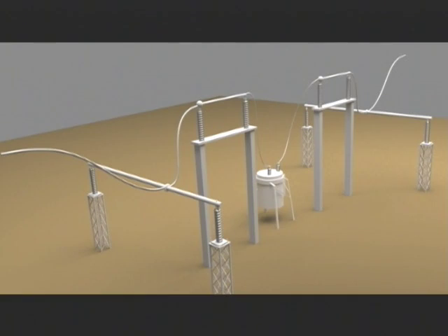Together in a switchyard. In this simplified diagram, we're looking at a single line in the switchyard. Now, as we've seen, breakers and disconnects usually come in groups of 3. Electricity comes in here, current flows through the disconnect, through the circuit breaker, and through the second disconnect to the load. In this case, the load is connected to a transmission line.